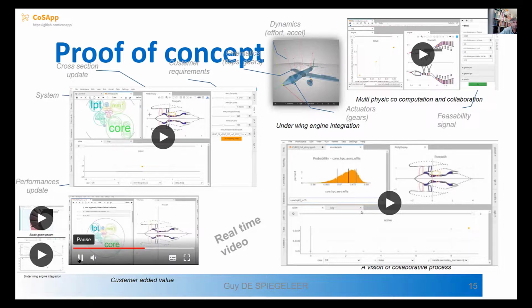What does the customer want in an engine? When you deliver an engine to an airframer like Airbus or Boeing, what they want to know is the potential life duration of the engine. And it's identified by the temperature you have to put in the combustion chamber to respect the thrust that is necessary to take off. So to adjust the thrust, you have to put additional fuel in the combustion chamber.